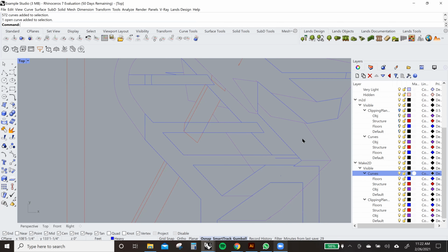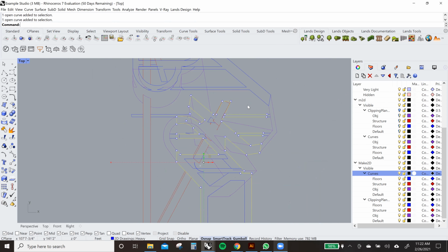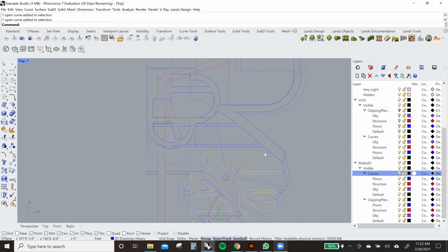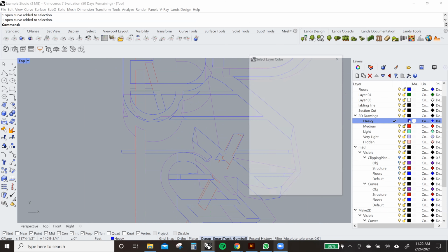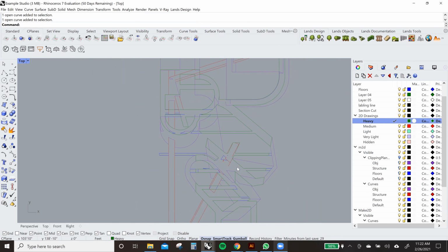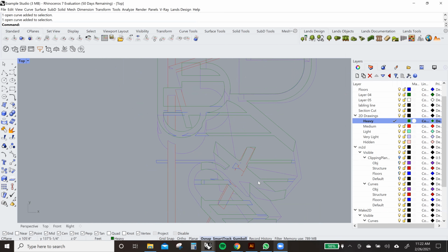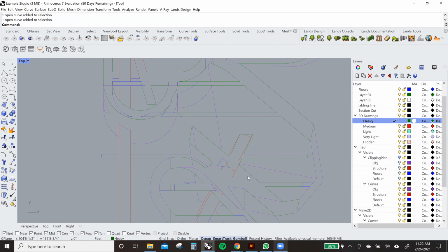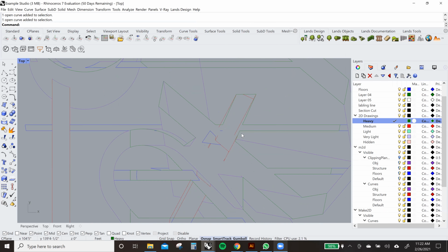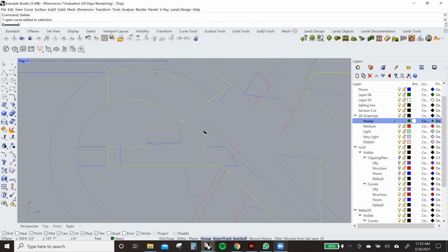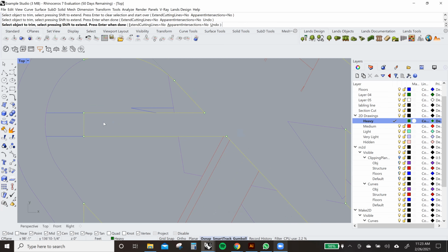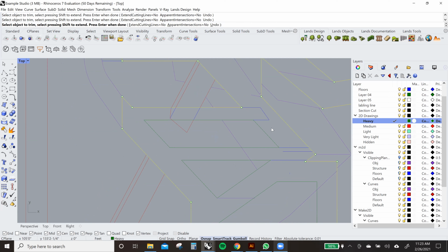So next order of business is to get back into these, I guess, behind the cut lines. Something that I noticed immediately is the closeness of this cut line with some of the other layers in this Make2D. So I'm just going to change that cut line so it's easily read and we know what is inside the form and what is outside the form. What is outside of the cut are things that we want to keep and articulate, and all the stuff that's inside are things that we want to delete and clean up. Use the trim command.